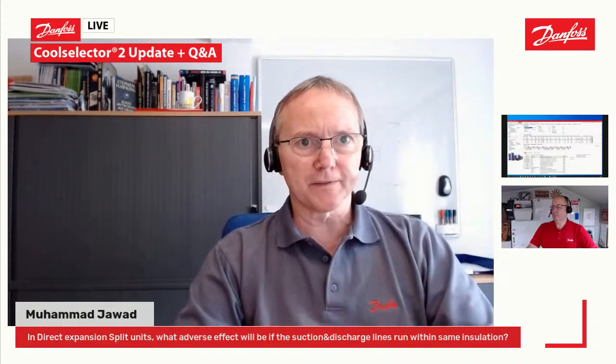Everything that goes into this area, you can calculate using a so-called superheat ratio. So there is a relation between the inlet temperature and the evaporation temperature that allows you to get to a certain superheat value that your expansion device adjusts. This is about 0.65. It can be a little bit more, a little bit less, depending on the design of the evaporator.